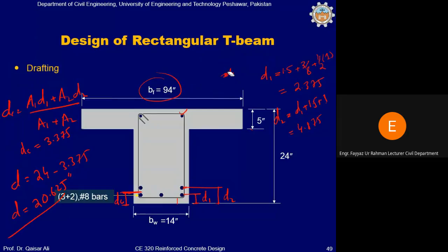Okay, now you can calculate the depth of the compression block based on the actually provided reinforcement.